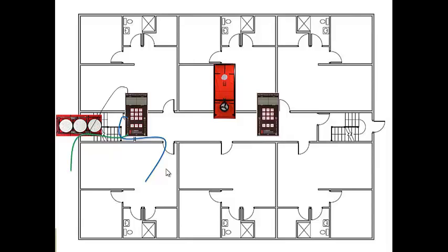So the way we would do that is we would do our baseline, and then we'd uncap the bottom fan and turn it all the way up. And then the second fan, we'll get the blade spinning on it before we take the rings off. Otherwise, if we took the rings off with the blades not going, the blades would spin backwards, and turning it up wouldn't get it to stop and turn around. So we need to get the blades spinning before we take the rings off to make sure that the blades don't start spinning backwards.